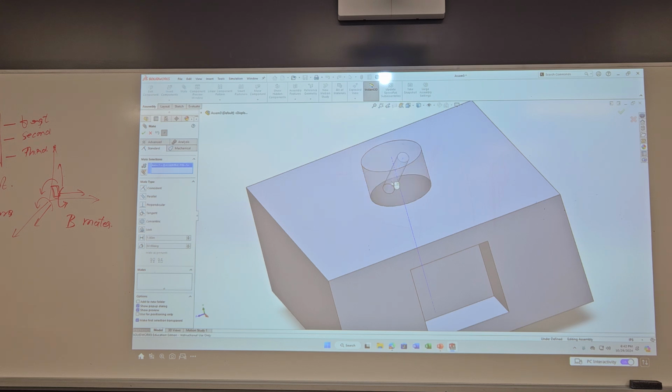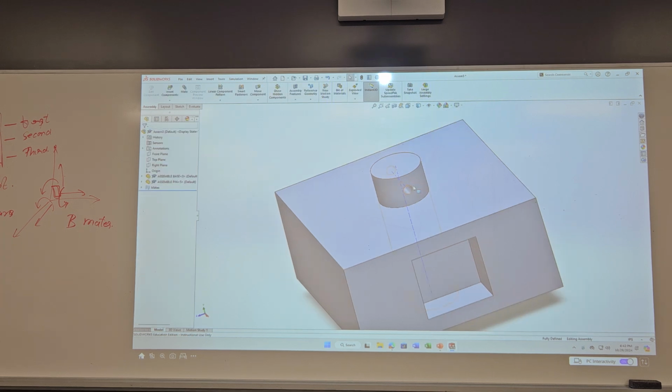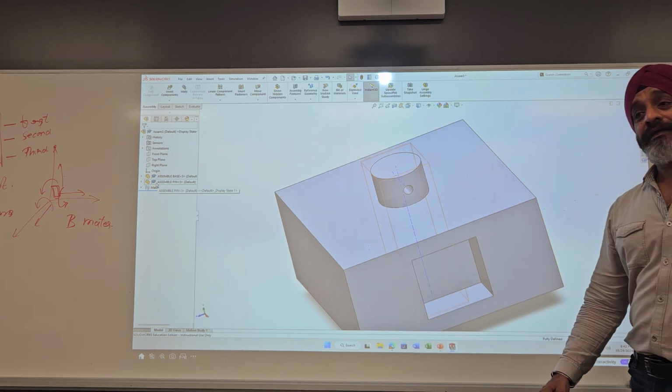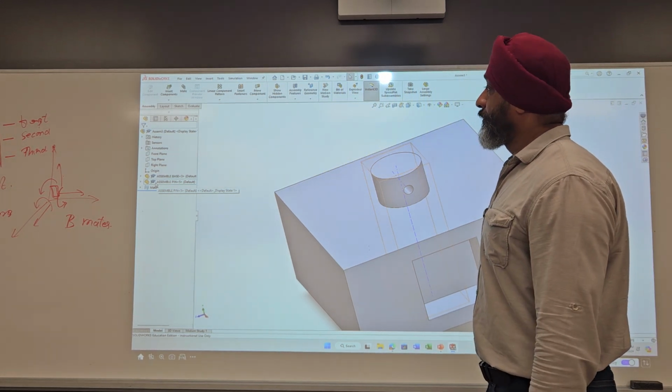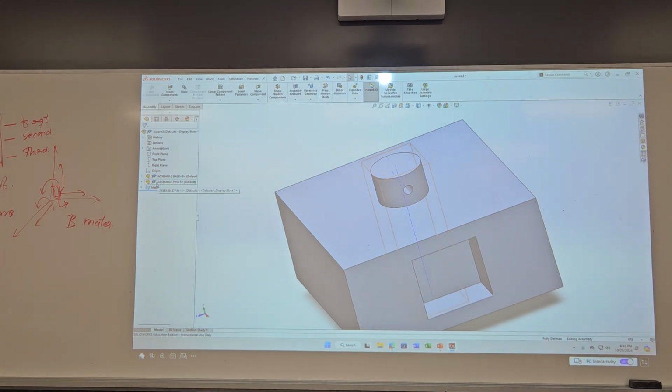So this axis, which is our hole, mated with, let's say, the front plane. And it's coincident because they were right there, because we selected our origin. Now you cannot turn it, and you can see your negative side is gone. Is it a must that we use the front plane? No, you can, let's break that and do it again.